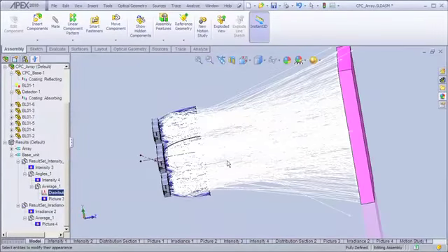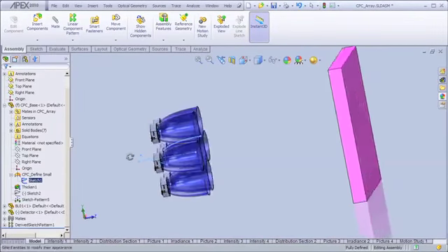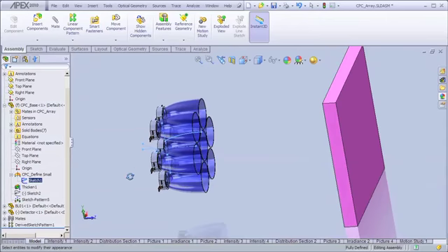The other thing to mention, the CPC is an equation-driven surface. So in this particular case, I've defined a CPC for a 3 millimeter input radius and a 30-degree output cone. If I need a system to use a different sized LED, so a different input aperture size, or if I want a different angle of output energy, all I need to do is go in and modify the equation-driven CPC definition, and I have my new CPC.